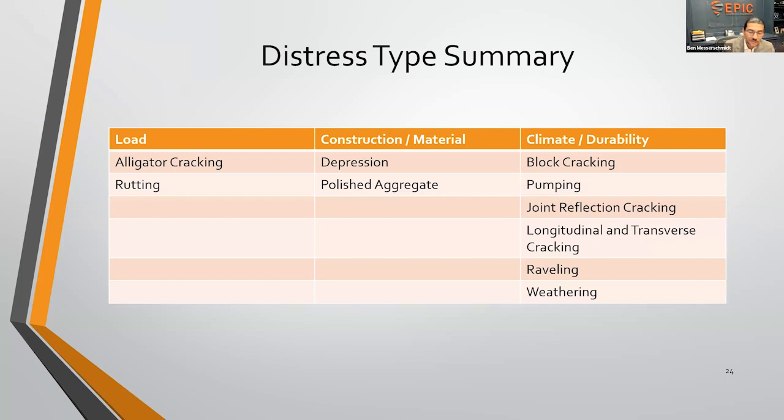If you're going to have, let's say, a heavy chlorinated or heavy chemical area, in all likelihood you're going to want to move towards a more rigid system. So move towards a Portland cement pavement as opposed to just keeping with asphalt pavement. And also the curing aspect of things is going to be very important as well.